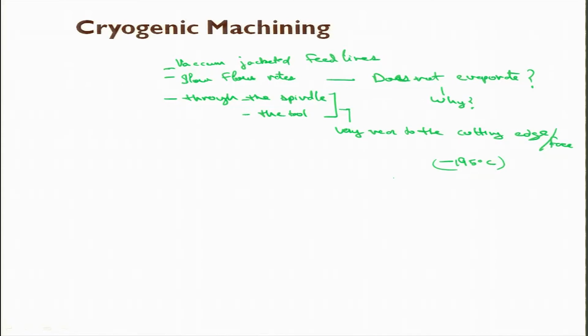So, the refrigerated state allows the tool to be pushed beyond its traditional limits. At very low temperature the tool performance becomes very good and it increases its wear resistance, and difficult to machine materials can also be machined here. Materials can also be processed.